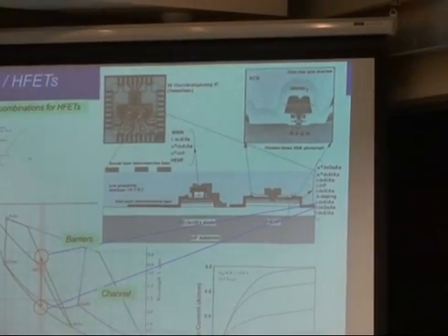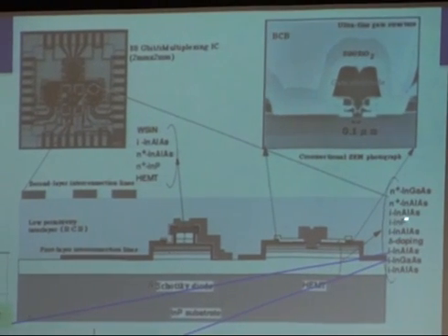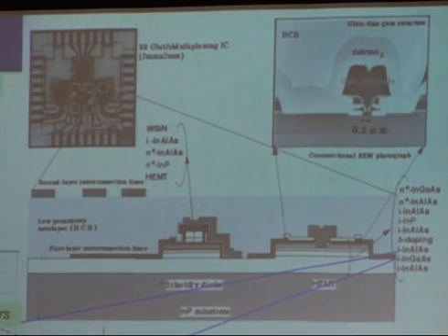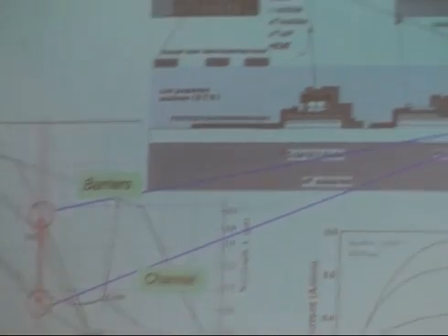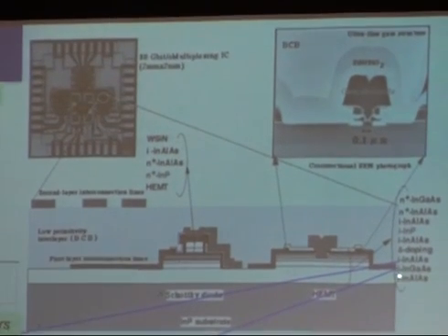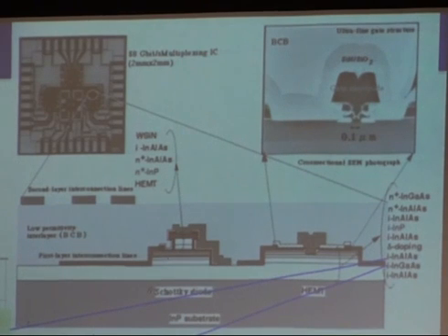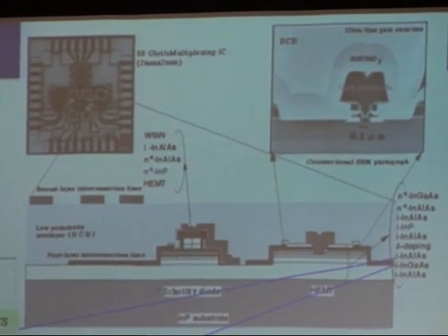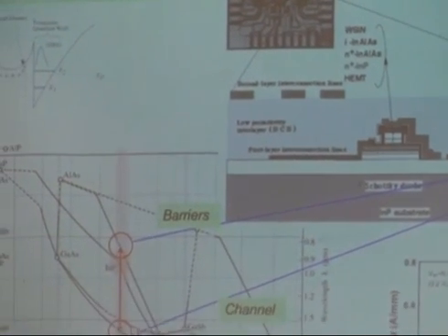And then the gate length here at the bottom of the footprint is about 100 nanometers, 0.1 micron, from source to drain. And if you zoom in here, you see there's indium aluminum arsenide, as I was mentioning. Indium aluminum arsenide is the barrier layer. And indium gallium arsenide is the quantum well region. So this is indium gallium arsenide, and that's where your electron channel is actually sitting for the conduction. And there are all these details. Here's how the transistor looks, and this is actually used often now.